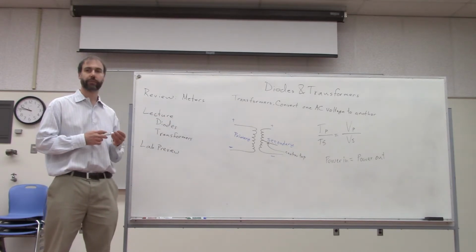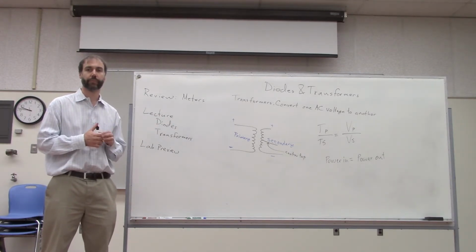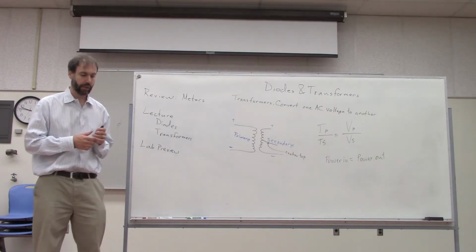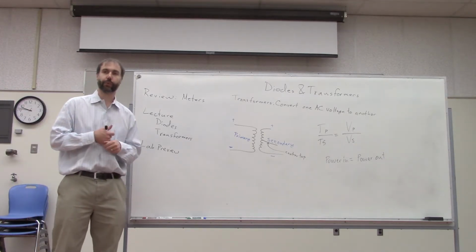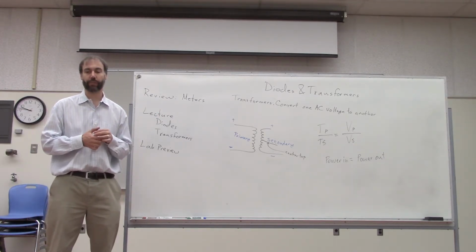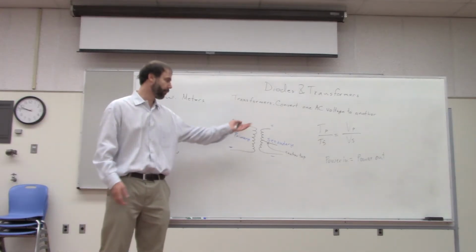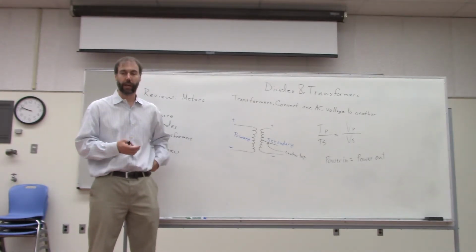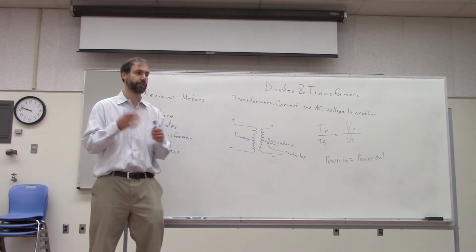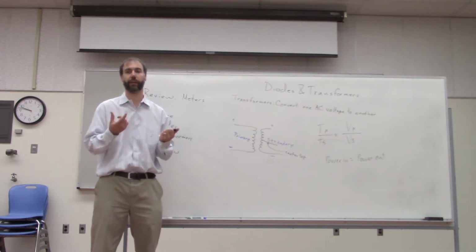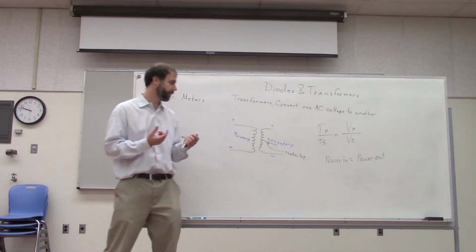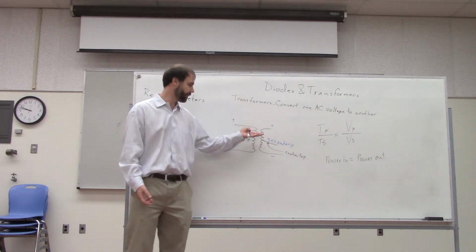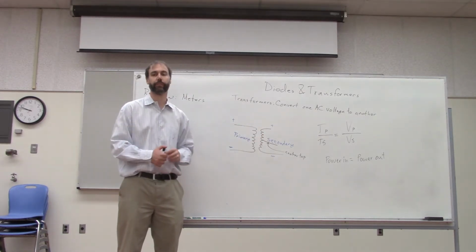Any questions about that? Yeah. Why do you want to scale the voltages? There are different applications where you need it. Some types of power supplies need this type of configuration, and we'll talk about that next time. Also, for things like wiring a house, most of your light bulbs, computers, things like that need 120 volts, but some appliances need 240 volts. You can use a center tap and get both voltages that you need.